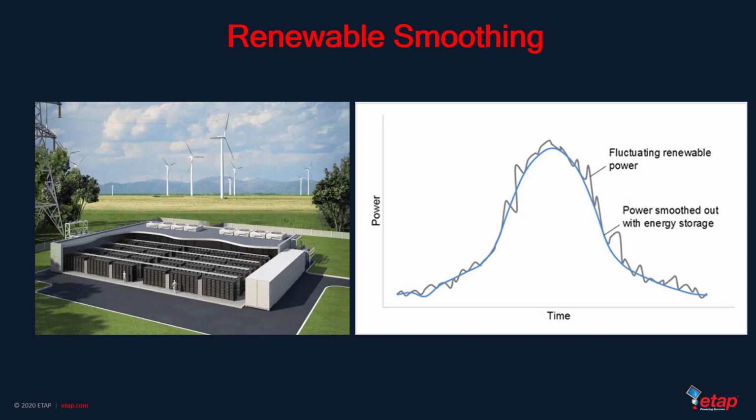Today, the grid operator sends a signal to power plants approximately every 4 seconds to ensure the total amount of power injected into the grid consistently equals the total power that is drawn or demanded. Because wind and solar increase the magnitude of sudden power generation shortfalls or excesses, the grid operator requires more reserve power ready to respond at a moment's notice to ensure the grid remains balanced.